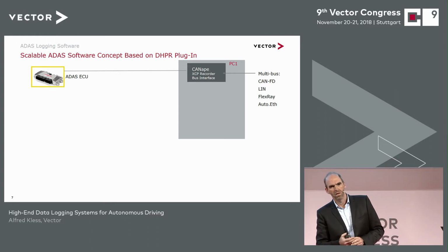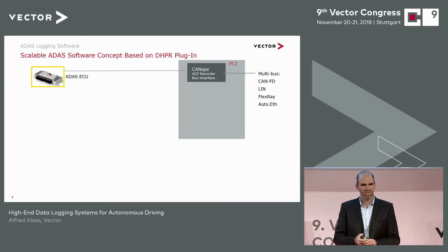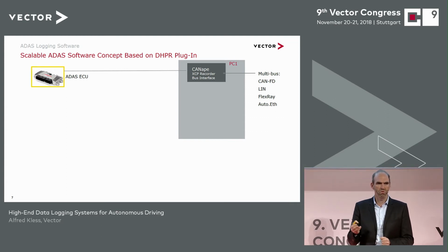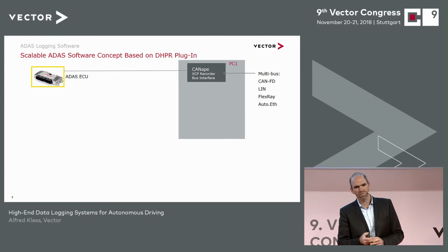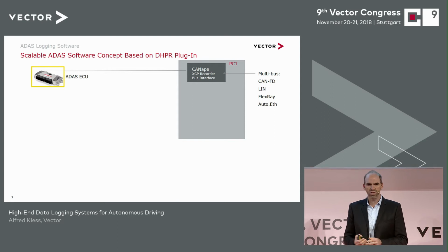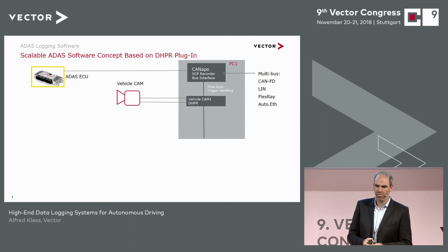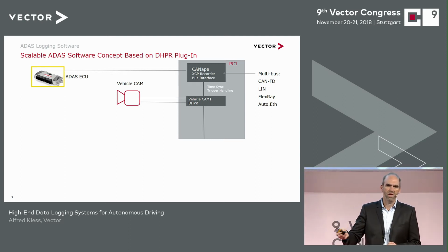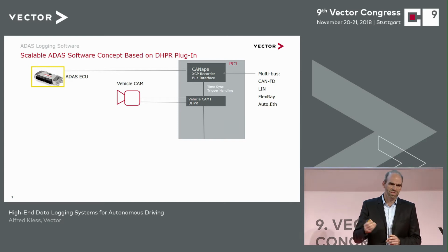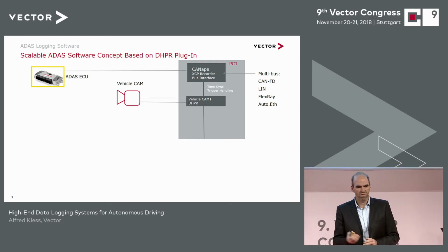So we've got the classic CANoe software, where I do have XCP interfaces that I connect, or bus interfaces. This is where the entire visualization goes. But CANoe in release has got a release cycle of once a year, maybe a couple of service packs. But development is so highly dynamic in autonomous driving that almost by the week I have to integrate new sensors. For that purpose, we have developed so-called high-performance recorders. They can be started and stopped by the main CANoe. They are time synchronized, with a plug-in interface where new measurement technology or new interfaces can be connected very quickly.